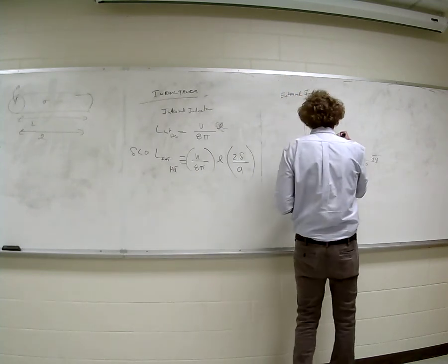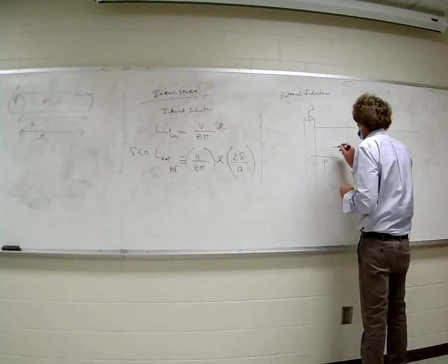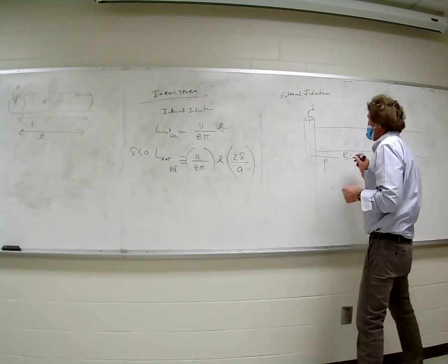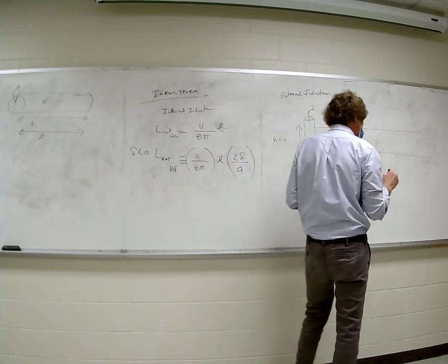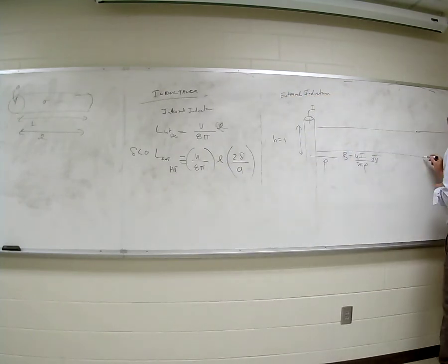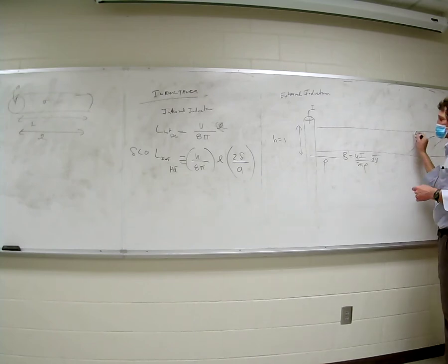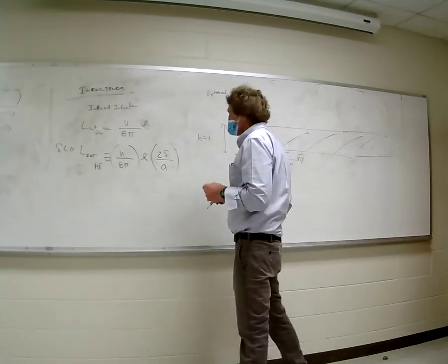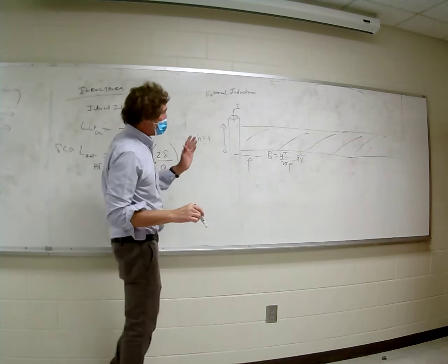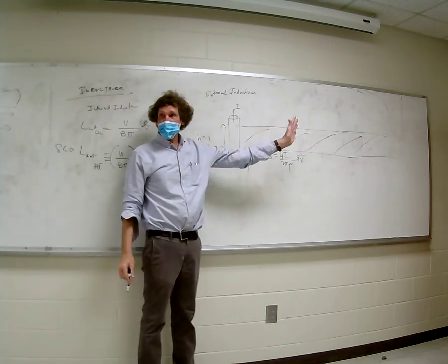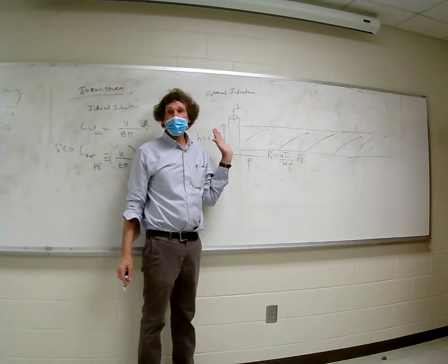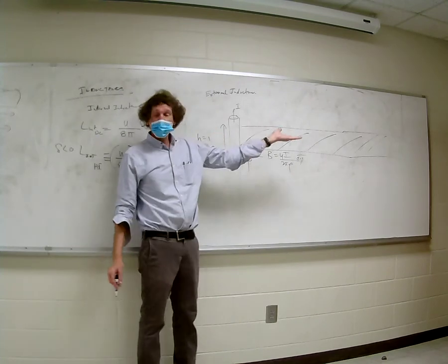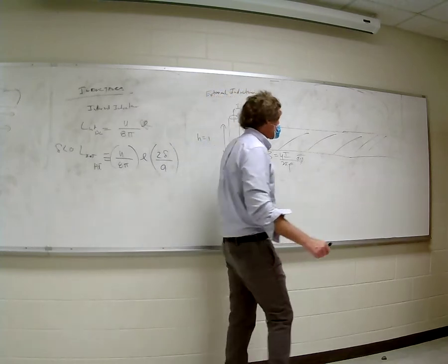So if we just theoretically took a look at this, take something that's got a thickness of, or a width of 1, just call it h equal 1. And if I want to figure out the total amount of magnetic flux linked there, you're going to see how this thing blows up. Are you with me? I'm going to integrate b dot ds over that entire surface. Can you imagine this in your minds? That would be the amount of magnetic flux penetrating it. It went out to infinity, right?